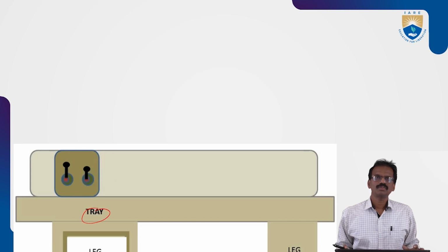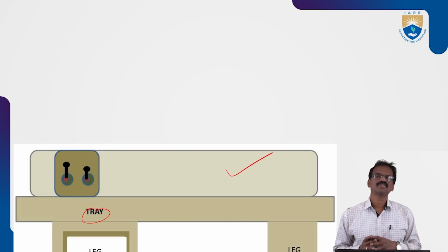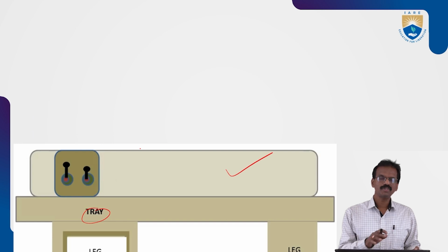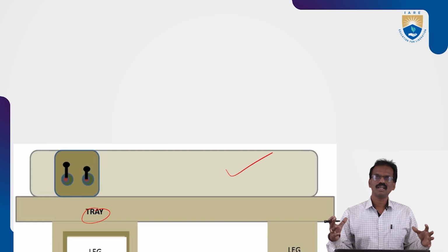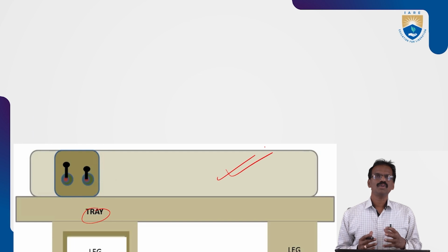On this base and legs sits the bed. It is very important. The bed has some guideways. On the top surface of the bed, you will see the guideways which are used to move the tailstock and the carriage also. Next, it has some hollows on the top surface of the bed. The main purpose of the hollows is to minimize the weight and also to collect the chips.